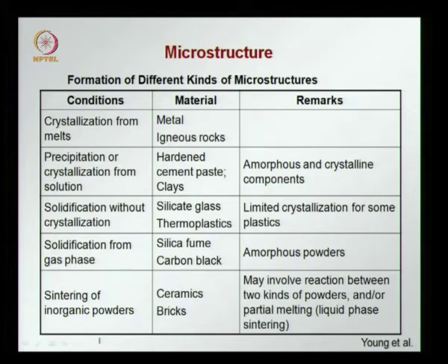This makes it possible for this silica to react with calcium hydroxide, that is a byproduct of the reaction between cement and water. The calcium hydroxide reacts with the silica fume to give us a form of calcium silicate hydrate, which acts as the binding material in concrete.